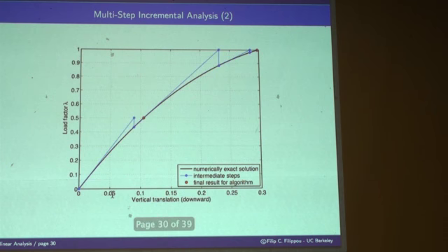In other words, I don't insist on corrections. I just say I'm happy with the red dots. Somebody may say, wow, what a stupid method. Right? Only the initial stiffness is one linear step. In other words, linear step after linear step, but updating the stiffness. It always converges. And if the step size is small, it is pretty good.